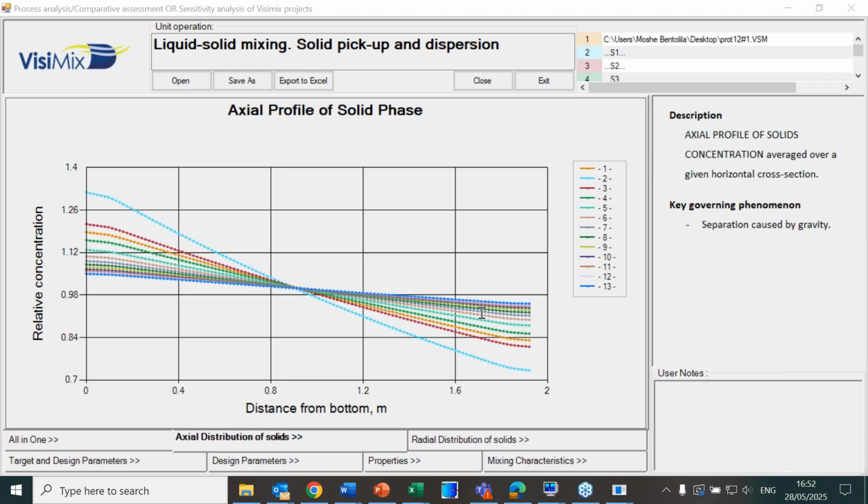Yes, another question. Is it possible to use scaling up from lab to plant scale with a scale-up factor? Yes, but when you are talking about a scale-up factor, normally you are talking about one parameter. Take care when you are doing it, other parameters should be similar. Okay, if I do a scale-up factor for mixing times, who tells me that the solid distribution will be the same? And maybe the solid distribution is critical, or the mass transfer, or the drop size. So take care of it.